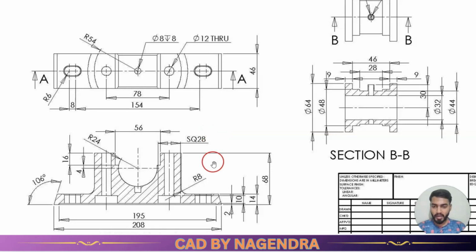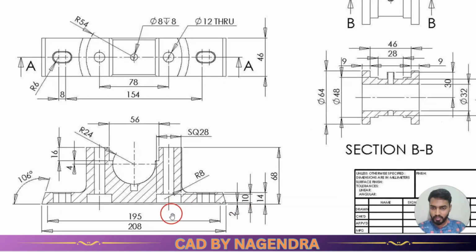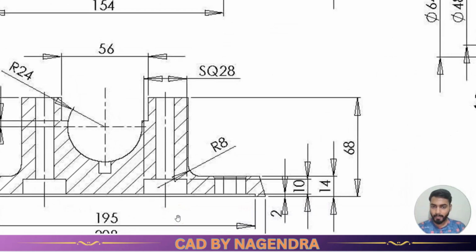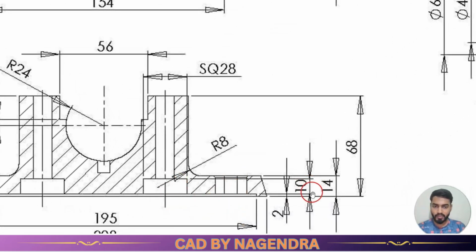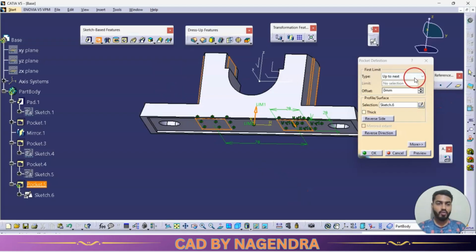So this pocket height we are having here, as you can see, we are drawing profile above this 2 mm. So total depth we need here for this pocket we are having 10 mm. So let's make here 10 mm this pocket. Let's check this. This is through all, and this we are having 10 mm. So we can make it here a dimension of depth 10.